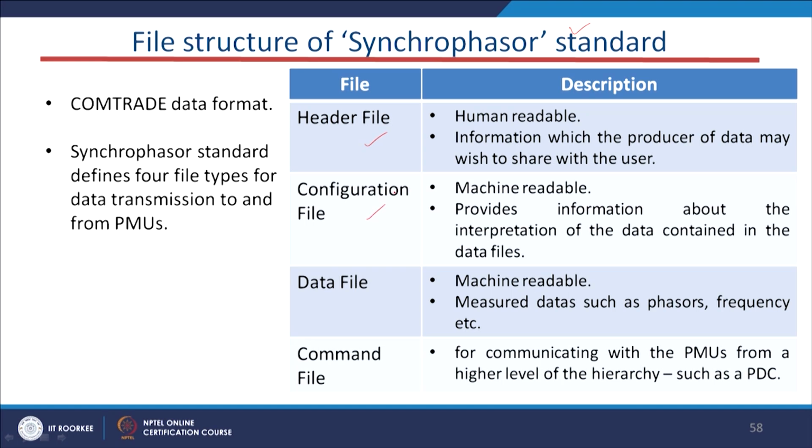And this is basically the file structure of the synchrophasor standard: the header file, the configuration file, the data file, and the command file. These are the files present inside the PMU, and the data files are sent to the PDC.